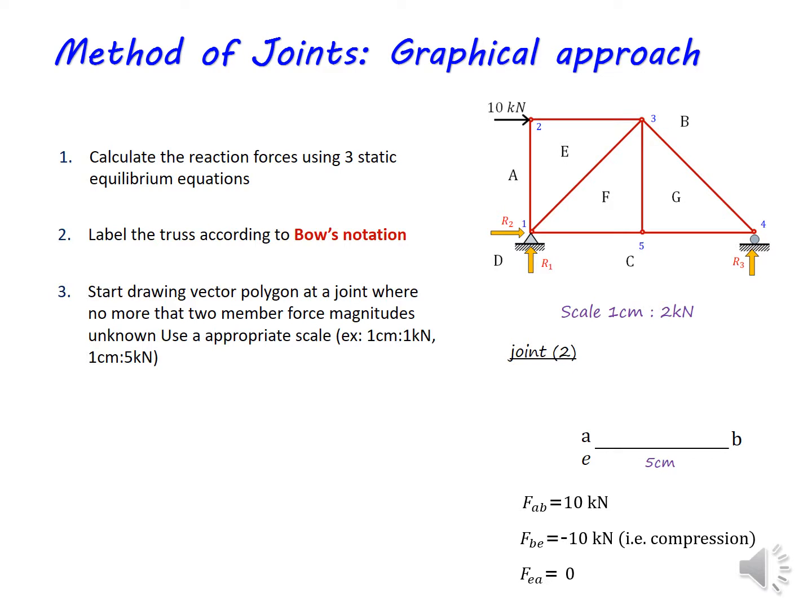As we can see, A and E are the same point, which means the magnitude is 0. And what information can we get from that? That the member force of member 1, 2 is 0.